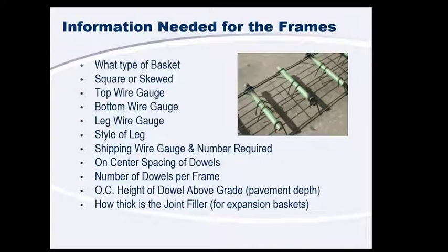Now this is in case you're not using a dowel bar inserter. If you're just using conventional baskets, there are a lot of different options for the basket itself. You can see the list there. One other mention on the dowel baskets: when you're placing dowel baskets, some states actually require you to cut the shipping wire.